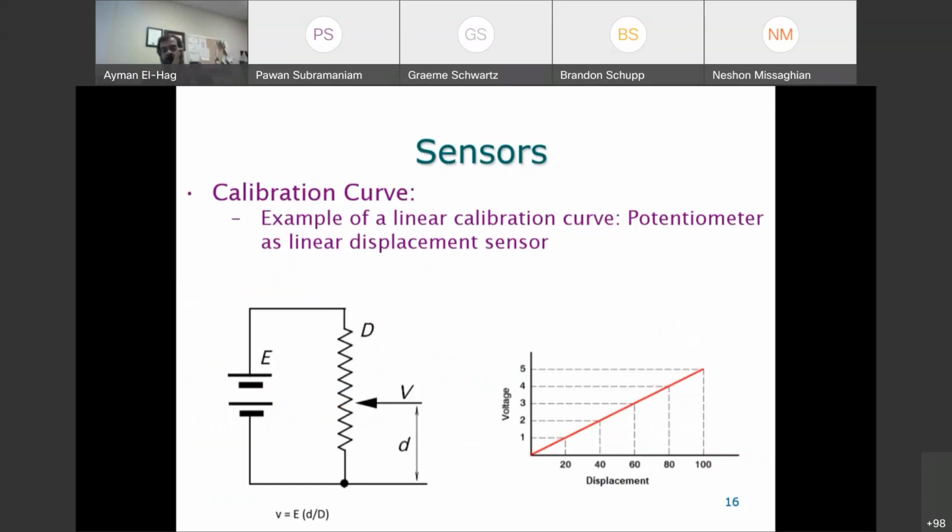Now, I mentioned the following. We are converting a physical phenomena into an electrical phenomena. So, for example, I am measuring voltage. I showed you the thermocouples. There is a temperature, this may be 60, 70 degrees. I am measuring a voltage, let's say 20 millivolt. Okay? I'm not interested in the voltage. I am interested in the temperature. But this voltage is only an intermediate stage. So I need to go back to what I am measuring.